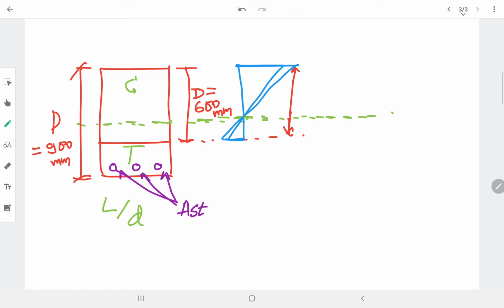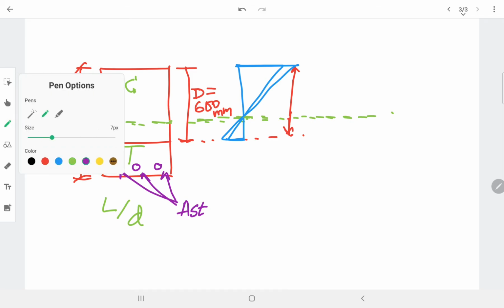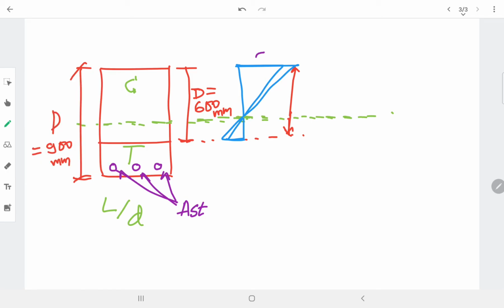When the area is reduced, the load over a certain area will change. So the area is less, the load is as it is, and that leads to higher stresses and higher strain. Here higher strain means the compressive strain is quite high as compared to tension.